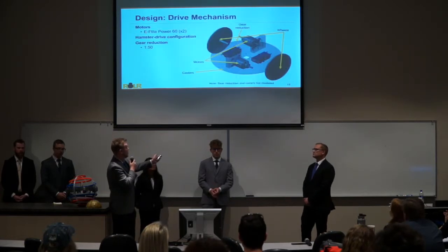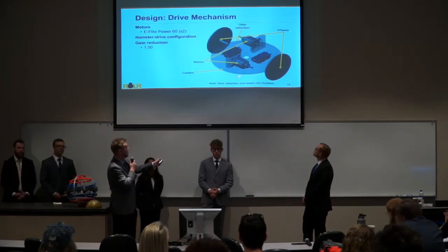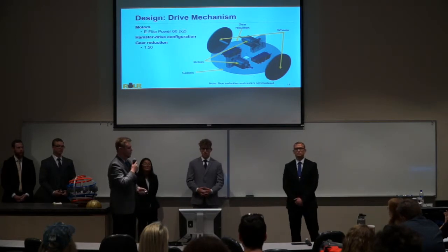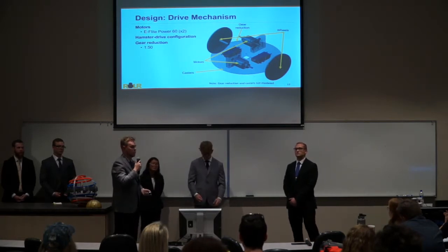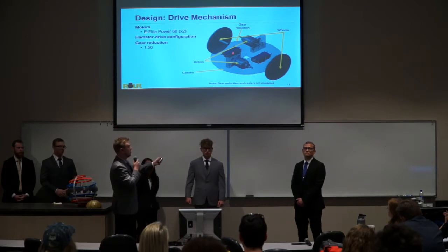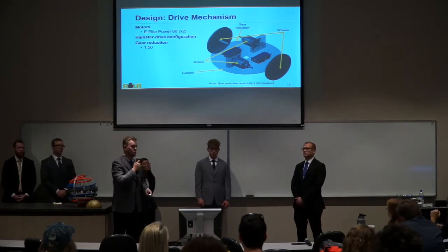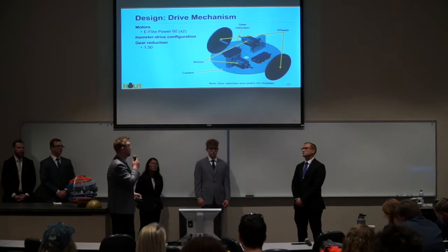And then with our motor selection currently, we did not originally have the torque requirement met in order to move rollers, so this will be employing a 1 to 50 gear reduction in order to give us the required torque to traverse up and down roller hill with no issues.